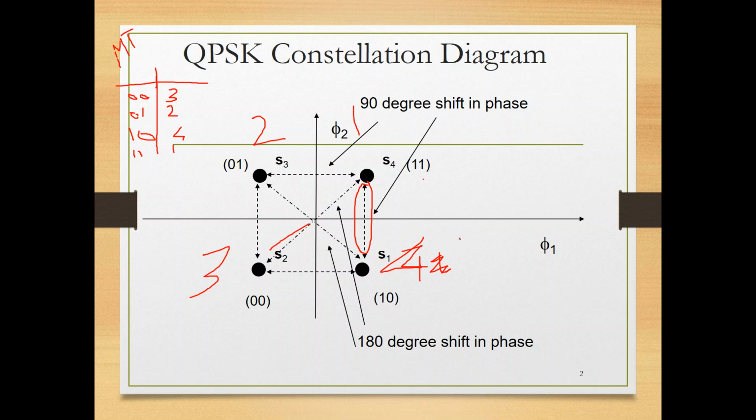And this also causes sudden fluctuation in the amplitude of your signal. Now, this kind of fluctuation, we don't like it in practical wireless communication system design, because this sudden fluctuation causes a sharp transition in the amplitude of your signal, not a smooth transition. Everybody knows that sharp edges, for example in rect pulses, are impractical shapes. In reality, you cannot generate them. So imagine you are doing these sharp transitions, sharp edges. You end up having something like this, which appears like a discontinuous signal. And this discontinuous signal, when it passes through a power amplifier or a filter, causes a high peak to average power ratio.